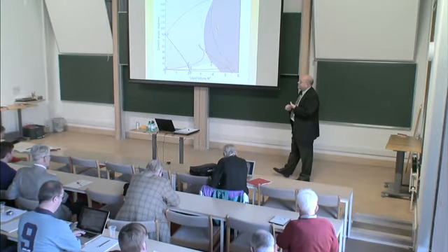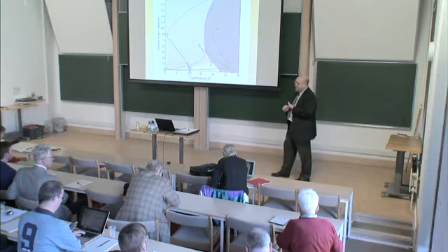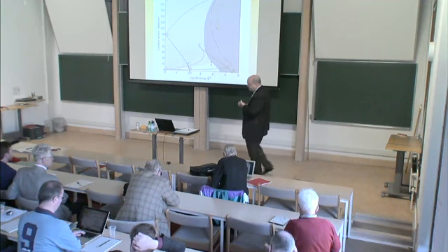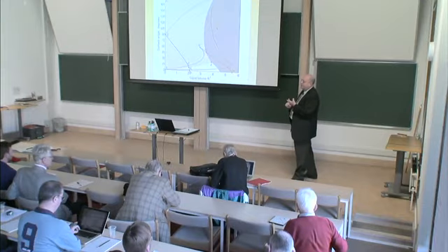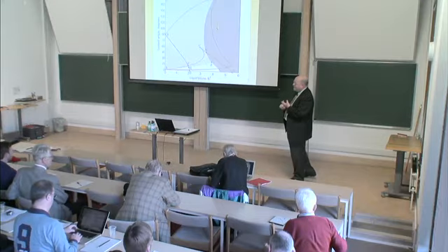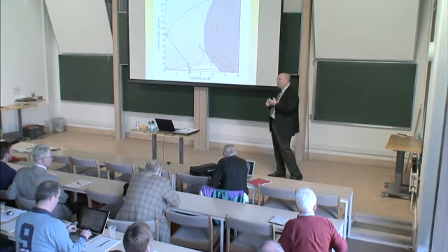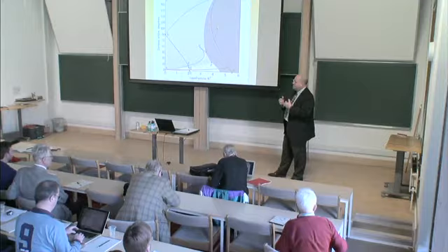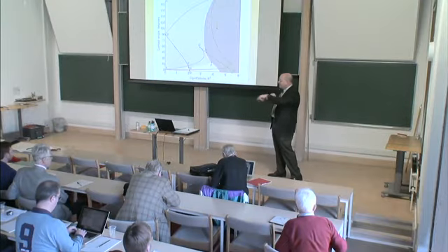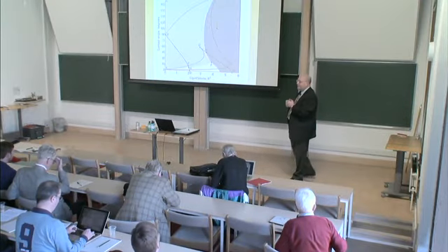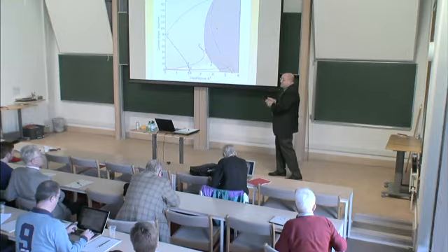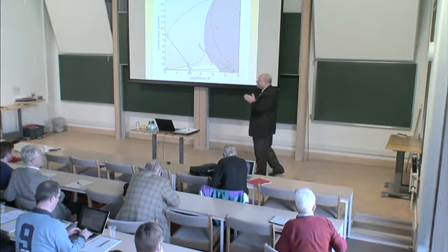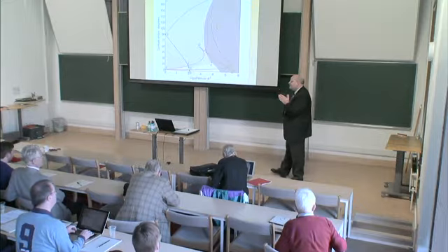Super non-wetting surfaces, and looking at them, I still think something's wrong in the Cassie and Wenzel limits, but it's not wrong enough to make a big deal out of. People say, well, it's small enough we could neglect gravity, and my point is, yes, even when you neglect gravity, you don't have a spherical surface because of the boundaries. In many cases, you have aspherical constant curvature surfaces. Yes, you have constant curvature, but a sphere is a very special case of constant curvature. So I think there's work to be done there.